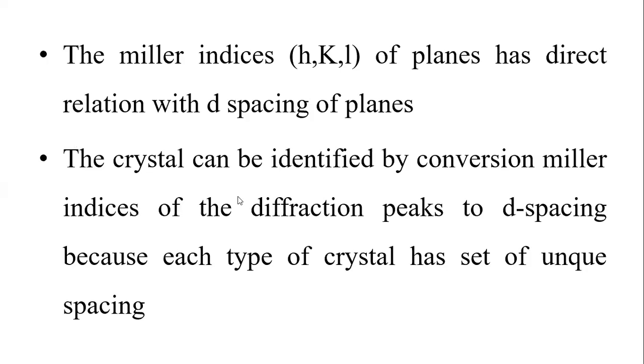The Miller indices of planes have a direct relationship with the d-spacing of the planes. The crystal can be identified by converting Miller indices of the diffraction peaks to the d-spacing, because each type of crystal has a set of unique spacings.